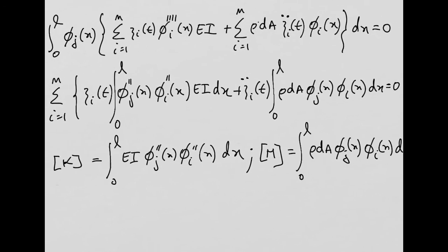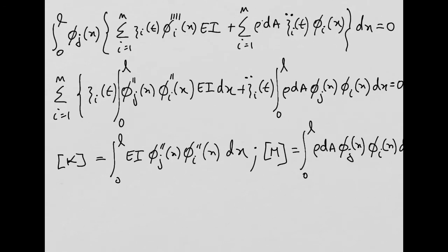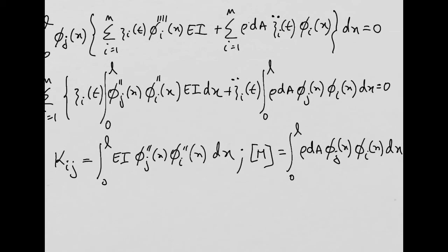So this is a matrix, of course. But if you don't want to do it this way, you can say this is the stiffness matrix ij component. Each ij component in your matrix, don't forget this i and j vary from 1 to n, depends on the shape functions i and j and the second derivative of the shape functions, right? So I think it makes a lot of sense.